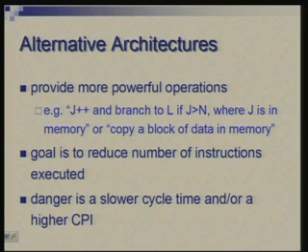When you say 2 gigahertz Pentium, that means the basic time reference is a 2 gigahertz periodic signal, and operations occur with each individual cycle of that clock. So, trying to include more complex instructions in the set may have a negative impact on the clock frequency. Okay. So, a fast clock is possible if you have simple instructions.